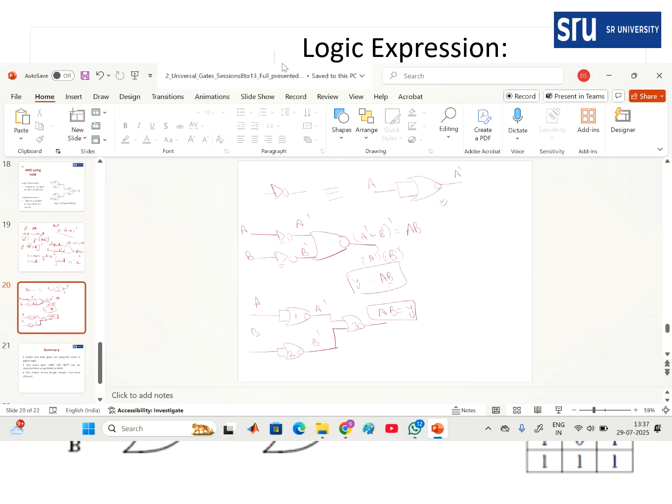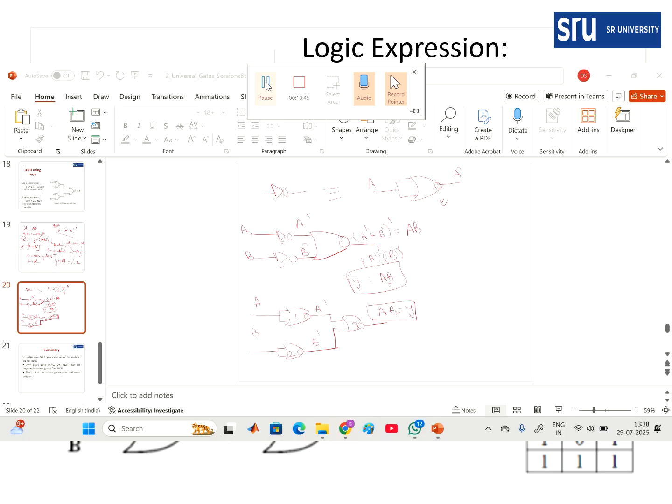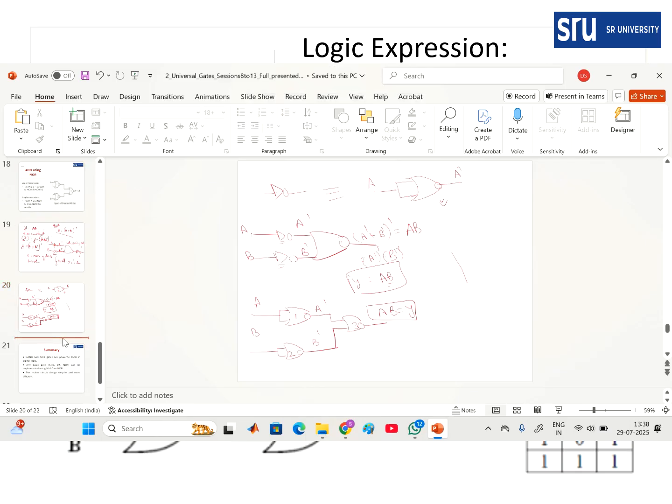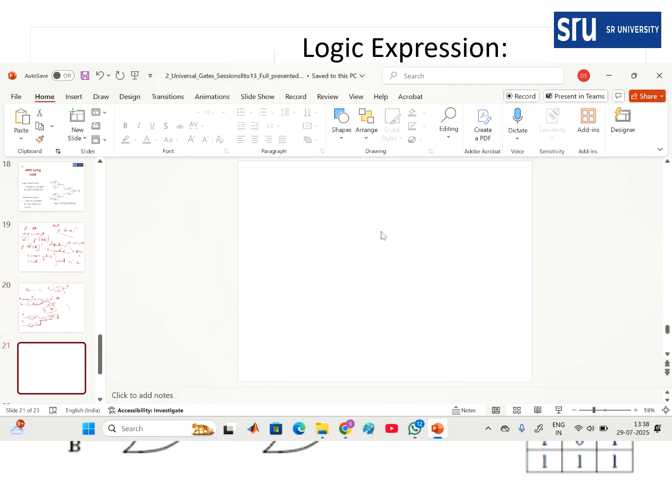Now, the same, we will consider the NOR gate IC. So I have already told you the NOR gate IC is a little different from all the other ICs. So first the output is available, output 1. Then we have inputs. Again output 2, we have 2 more inputs. Right? So this is the ground pin. NOR gate IC.